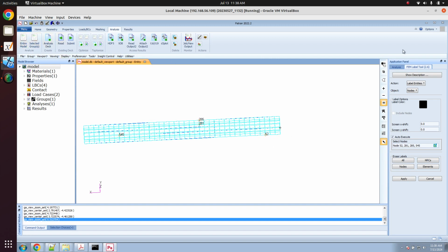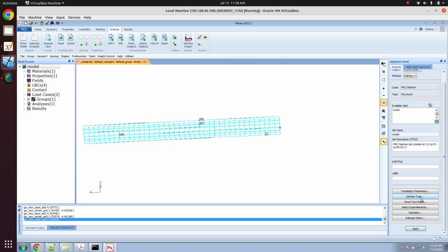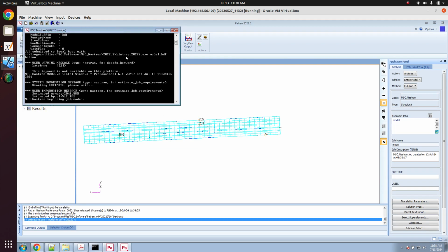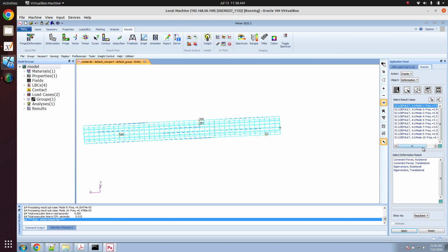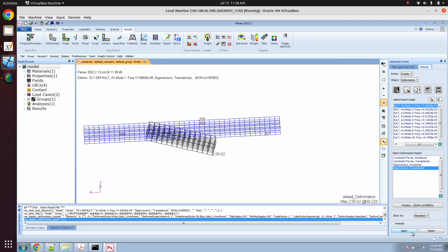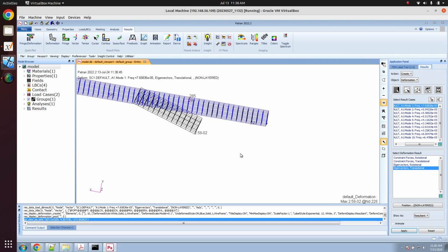Now, again, the easiest way to diagnose this issue is to go to a normal modes analysis. So let's go ahead and do that right now. And then after that's done, let's go ahead and import the H5 file, and let's go ahead and look at the mode shapes. So when you have a natural frequency very close to 0, that means you have a rigid body. These rigid bodies or mechanisms can clue you in on what's going on. So here, let's look at the first mode shape. So this is the first mode shape when it's not animated. Let's go ahead and animate it.